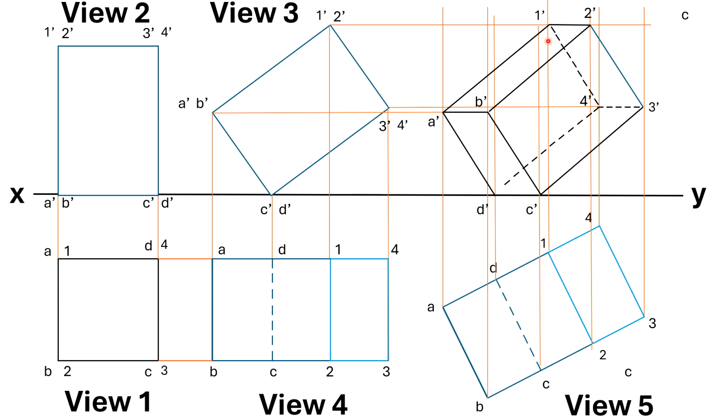So all these lines you can mark as hidden lines. Hidden lines will be marked with dashed lines. So with that, the projection of this solid and identifying the hidden lines are over, and this becomes view 6. So with this, the projections of this entire solid is over.